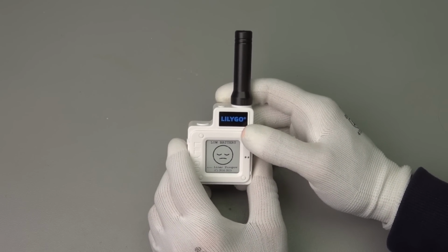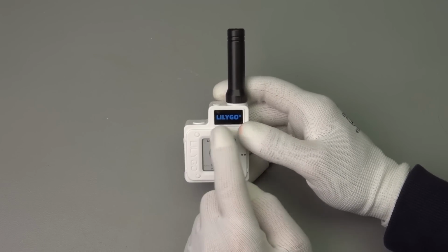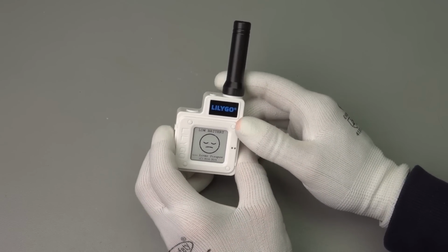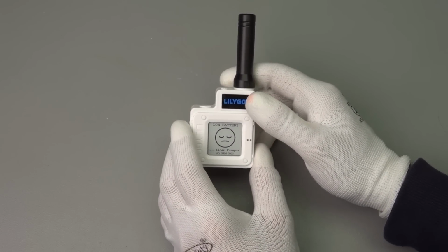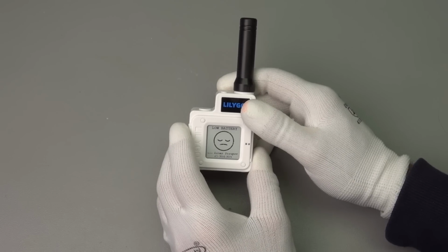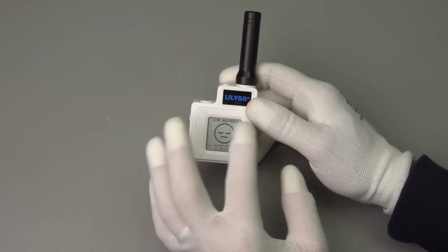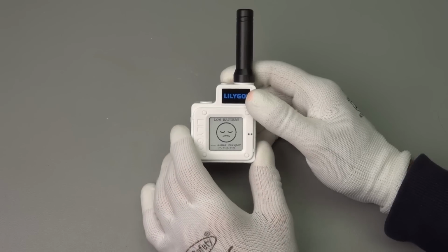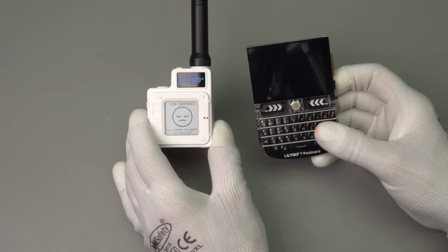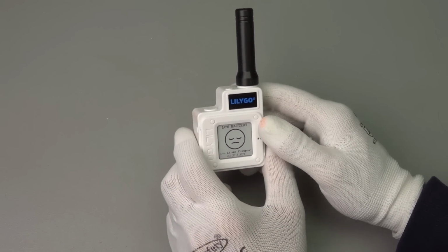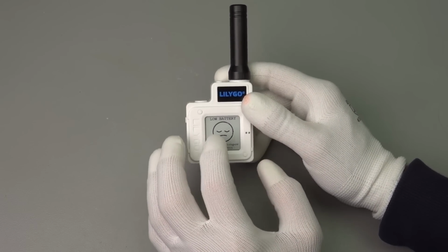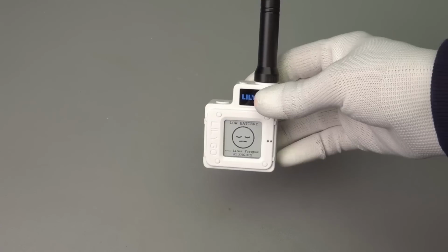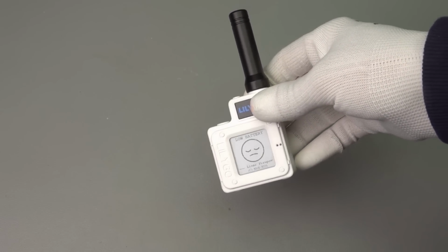Another nice device I purchased from LilyGo recently is a LoRa device also, but it has no ESP32. It has an NRF from Nordic. This one has no Wi-Fi, but it has extremely low power consumption. It has Bluetooth, and it has an e-paper or an e-ink display, and not a power-hungry display like this one. Now this one runs for quite a long time, a few days I think, and you see it even displays something if the power is off. This one, by the way, has GPS, so it's an ideal tracker.